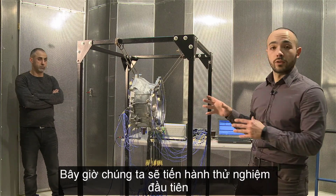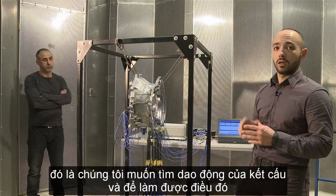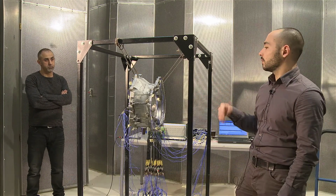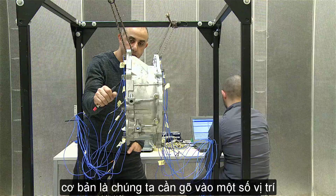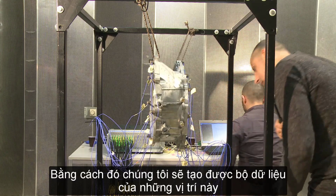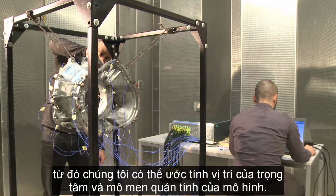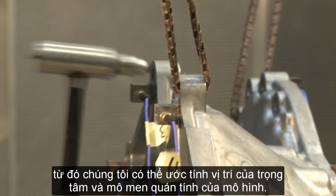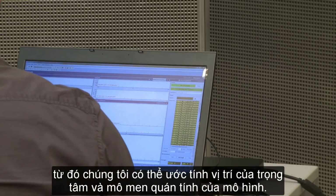Now, what we're going to do first, as a first test, is that we want to acquire the rigid body properties of this structure. And to do that, basically, we need to impact at several of the locations where we have the accelerometer. By doing that, we will create an over-determined set of equations from which we can estimate the position of the center of gravity and the moment of inertia of our structure.